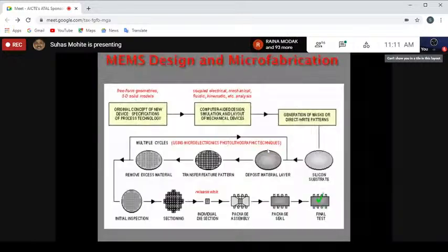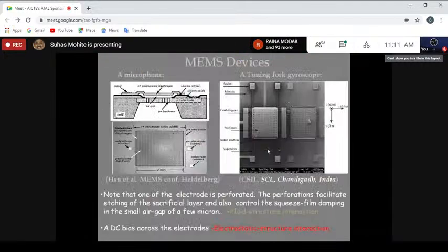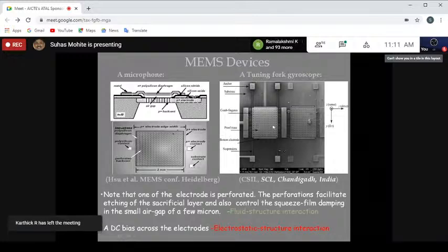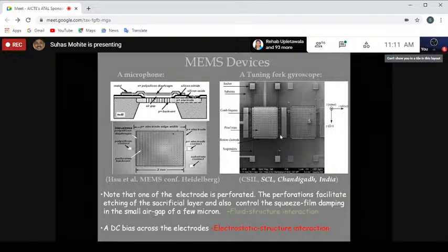Yeah. Certainly. The only thing is, I was asking you that small question, that these holes are for sending the agent, and then the agent will remove the material around the hole, and then the entire material will be removed, and then this particular plate will be released, and it will be freely oscillating. These beams are also released, and this particular end of the beams is anchored, and therefore this particular plate can now oscillate in its plane, or it can oscillate out of the plane.